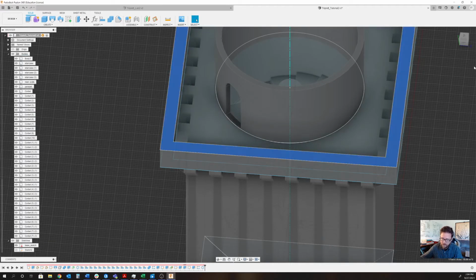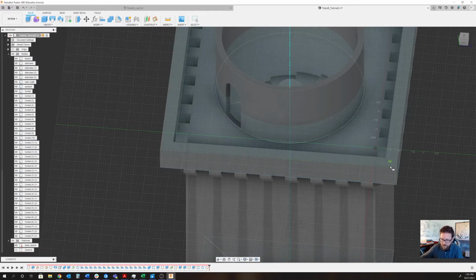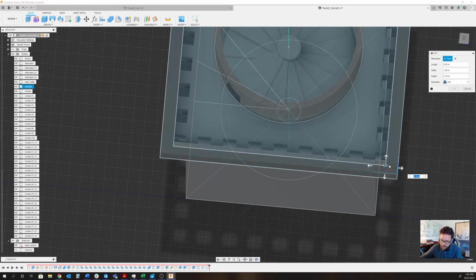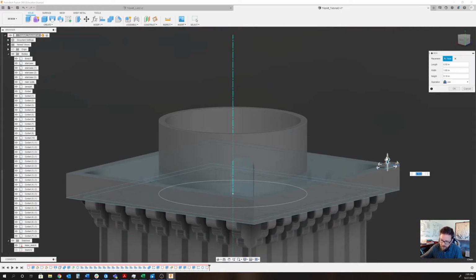Let's add a Merlin on top of here. That's going to be another new tool. We're going to go to Create. And instead of actually drawing a sketch first, we can just create a simple box right on top of that wall. I'll go, let's make it 1 by 1 by 0.5. 0.5 is fine. Hit tab and say 1. And our height will be 1.